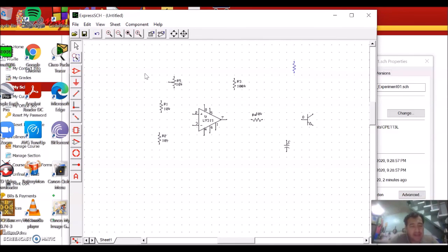What we do next is use the circle shape tool from the tool menu right here. Let us draw a circle around that resistor. Okay, we now have a circle at that resistor. And then select the whole object by using the arrow tool and choose component.